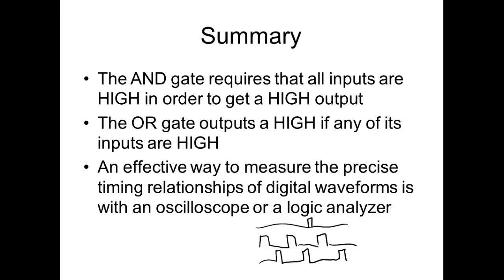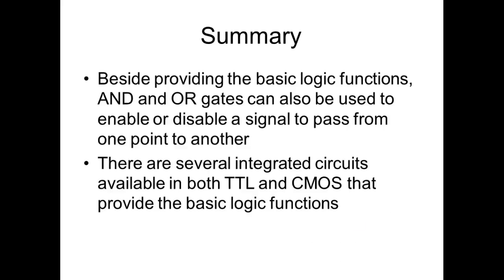So on these, if it was an OR gate and one input was pulsing, we know we're going to get pulses on the output, right? You understand that? An AND gate, though, you could have 8 inputs and all of them appear to be pulsing with a logic probe, but if they're not all pulsing high at exactly the same time, the output won't change.